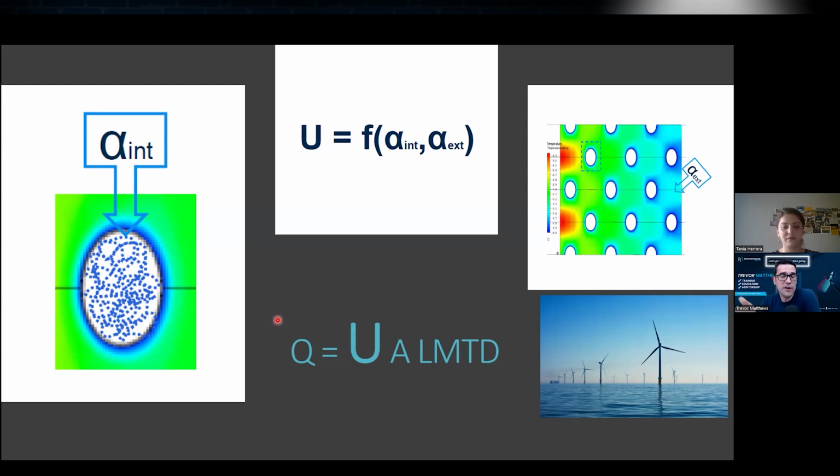But with different coils too, this will make heat transfer different. So there's larger coils and smaller coils. Some circuits you want to dehumidify that cold room more, and some you don't. So for example, a meat room, you don't want it to be pulling all the moisture out of the meat right away. So you'd have more of a humid room versus a dehumidified room. I don't know if I said that right.